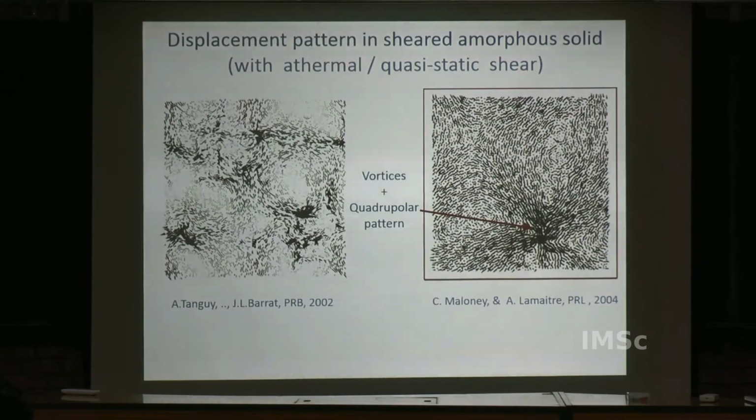Both in glass and amorphous material, a lot of research goes into trying to find whether there is a characteristic scale. On the other hand, in a perfect crystal, the characteristic scale is infinity, everything is ordered. Polycrystal comes somewhere in between, and the typical grain size gives you a characteristic scale. So, because of that, you do expect to see something different which you don't see here.